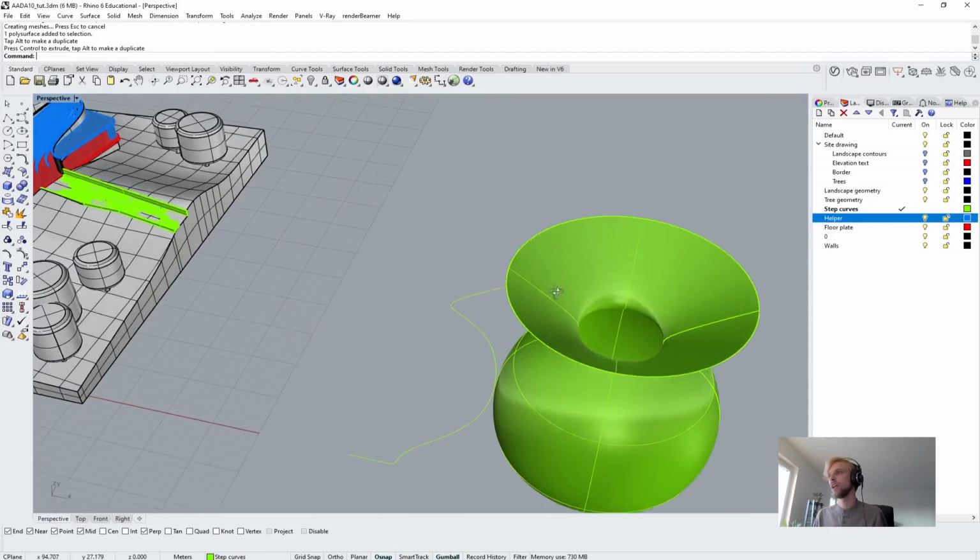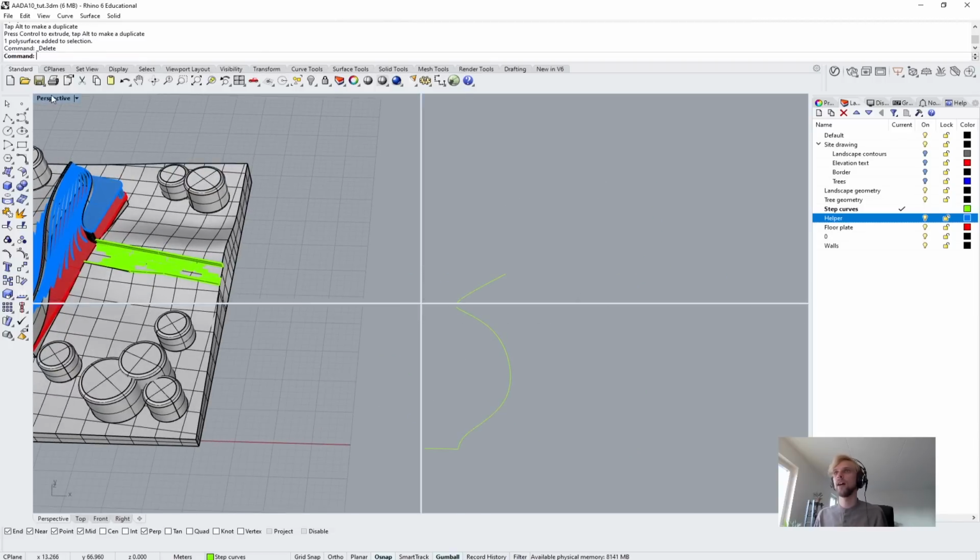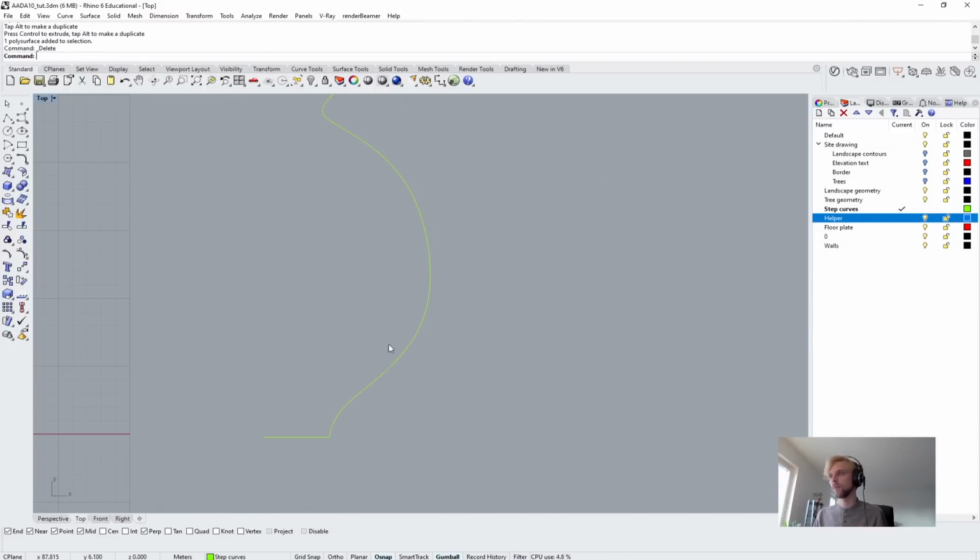Yay. If you want it to be not completely thin, you can mess around with, first of all, offset. So give it some thickness, 0.5, I don't know. Then use fillet corners, 0.5, I still don't know. For some reason it doesn't close off there. Let's close it off there.